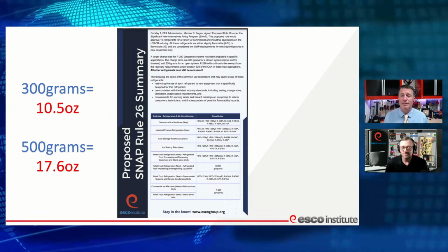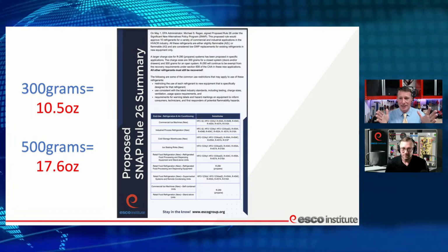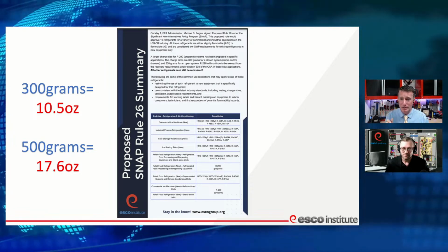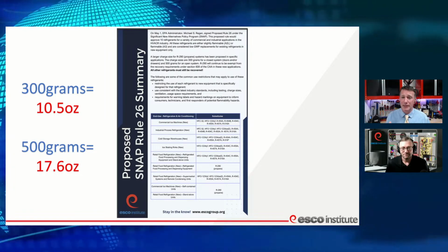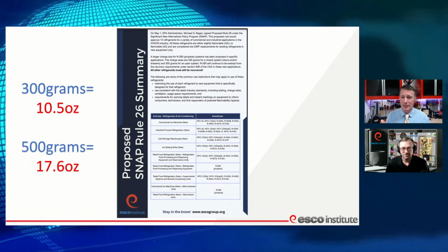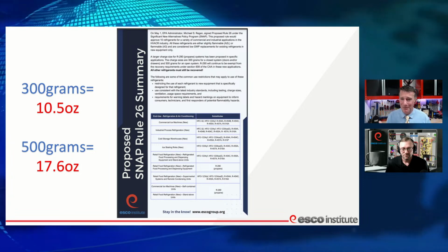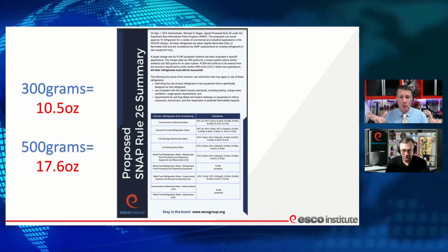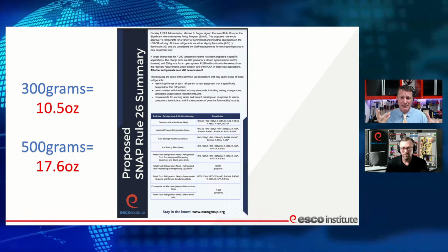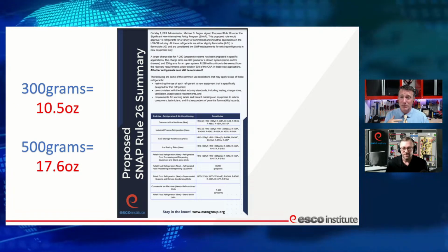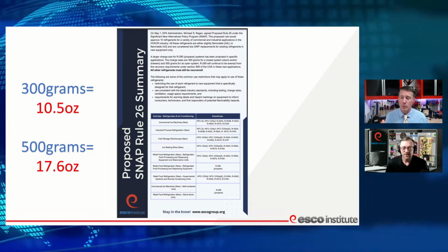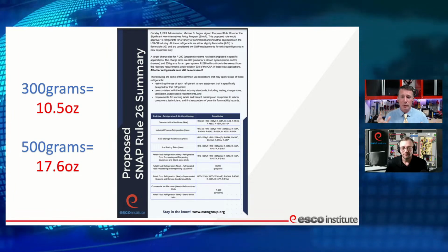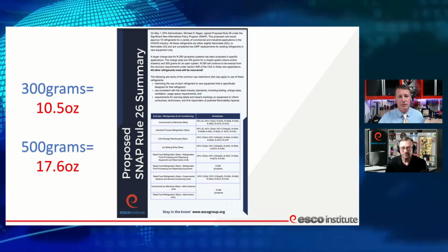Exactly. Prime example, I used to have one of my favorite pizza shops to work at, Eddie's Pizza down in Nineveh, Indiana. They had a little Ice-O-Matic ice machine in a closet with louvered doors, right? A little water-cooled condenser unit sitting in a closet. That unit, if I was going to replace it a year and a half from now, I would probably have to look at it and go, you know what? That's probably not the best candidate for an A3. I'm probably going to do a split system with R32 or whatever. With a 2L, correct. Yeah, with an A2L refrigerant. So we need to be aware of what those scenarios look like.